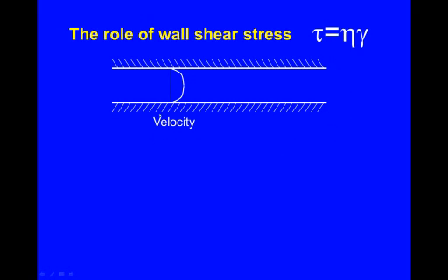When you have some velocity profile or material flowing through a tube or through an annular gap or any flow channel within a die, you end up with a certain shear stress profile in the system. And the shear stress is minimum where the velocity is maximum and is maximum at the wall. So you have a graph of shear stress.